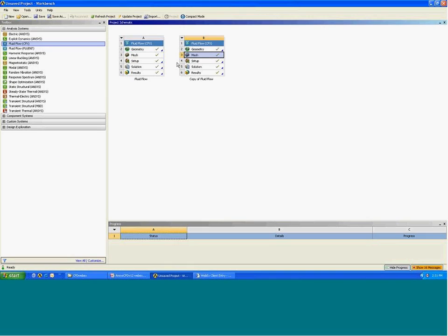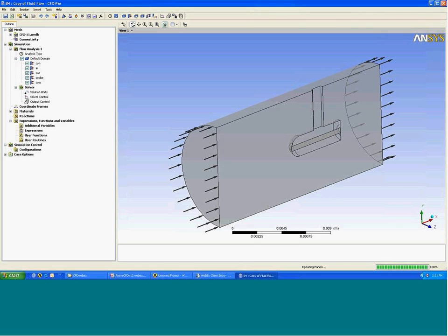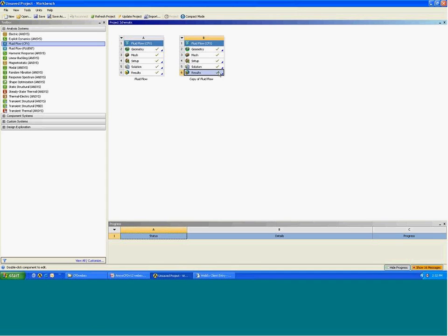And if we exit the mesh section, let's look at the setup. That will take us to CFX Pre, and to see, without going through the same procedure of bringing in a mesh and reassigning the boundary conditions and so forth, the setup is there. And the new geometry and the flow field is being updated right there to reflect the much smaller tube space, and much smaller internal flow passage inside the probe. So that is done. Of course, the solution is now complete. We can look at the solution to see what it's like as well.